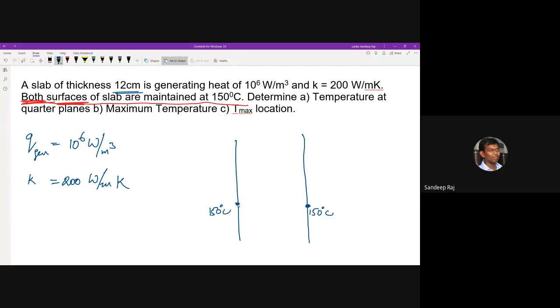The meaning of this is the temperature is varying like this. The temperature is varying because you have given Qgen in your question, so this must come into your mind, and this is how you should consider it. You should not say that the temperature is not varying at all. It's varying, but since there is a Qgen in the question, it is going to increase for some time and then decrease for some time.